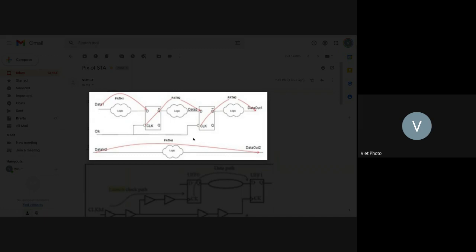I will present that later. But remember this one. Consider this as your block, and all the timing paths will fall into one of the four types here. The first one goes from the input of the block, without a flop, to here. The picture shows only one path here, but this is representative of all paths, because between flops you have thousands of paths like that.